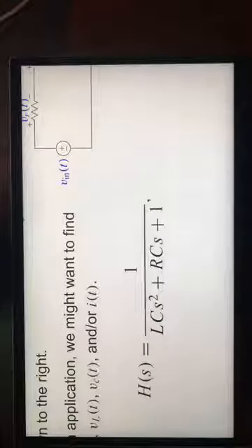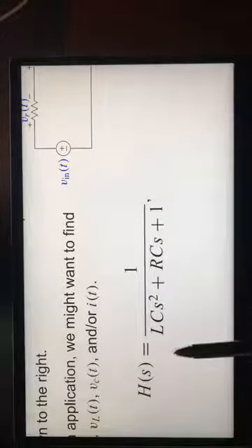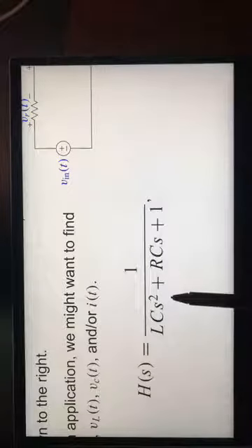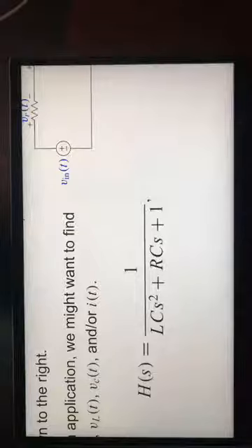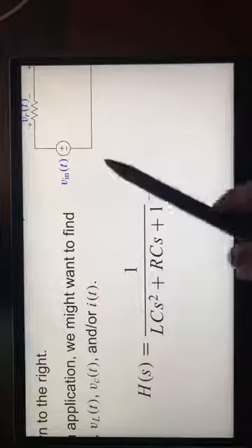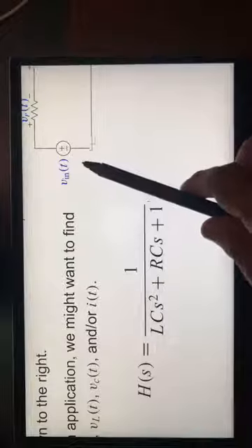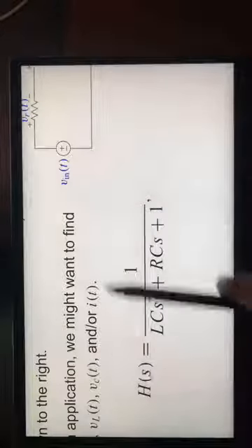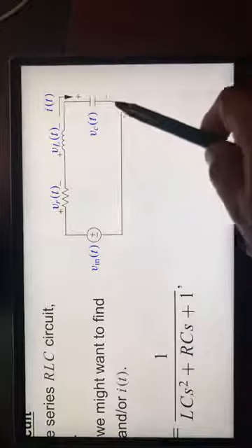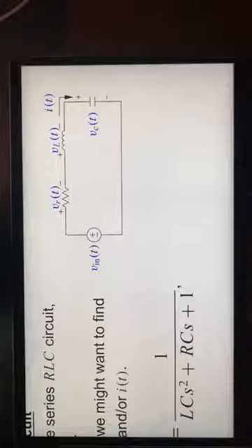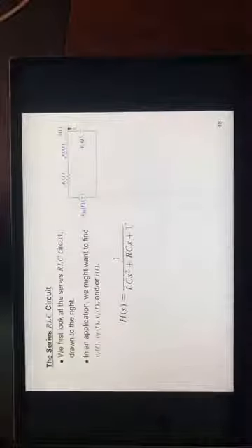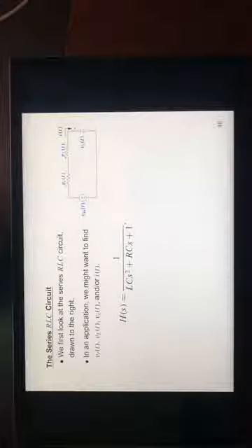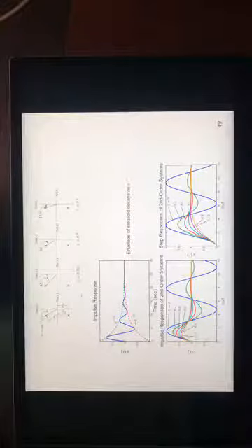Okay, and you might have done this in your first course in electronics, an RLC circuit, and this is the transfer function. So you can precisely implement this, knowing what we know now, as a second order difference equation. And you know how easy it is to implement a second order difference equation. So whatever input you give here, if you discretize and give that to a second order difference equation, it will give you almost the same output that you're expecting here. So circuits can be converted into a computer program by using the bilinear transformation.